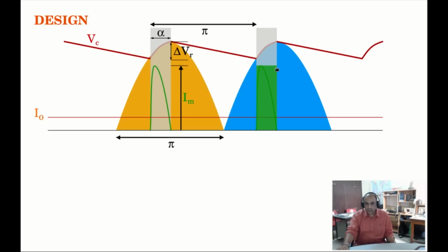If you consider this green rectangular box, if the current wave shape were something like that, and you design your components for this flat topped green rectangular pulse, then definitely it will handle the inner shaped pulse as it comes out of the capacitor filter rectifier.